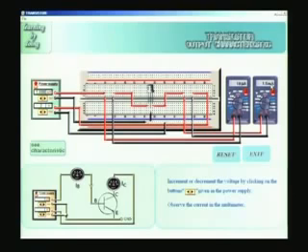At 2 volts, it is 1.5 milliampere. At 2.5 it is about 2 milliampere. At 3 it remains at 2 milliamperes. At 3.5 again 2 milliampere. So you can see beyond 2.5, even if I go up to 6 or 7 or 8 volts, the milliammeter shows the same value of IC, which is 2 milliamperes. That is what we saw in the characteristics. Now let me quickly come back to 0 for VCC and increase my base current from 10 microamperes to the next value, which is for example for 2 volts, 20 microamperes.